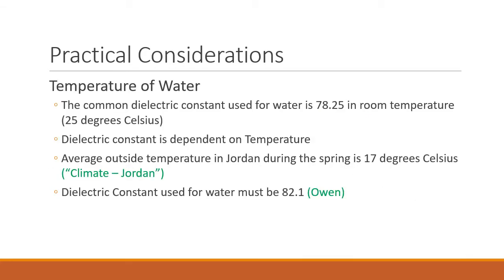The final practical consideration is the temperature of water. The common dielectric constant used for water, which we usually see in textbooks and on the internet, is 78.25, but that is in room temperature. And research has shown that dielectric constant is dependent on temperature. Now, the average outside temperature in my home country of Jordan during this spring season is 17 degrees Celsius. And at that given temperature, the dielectric constant used for water must be 82.1, which is what I'll be using